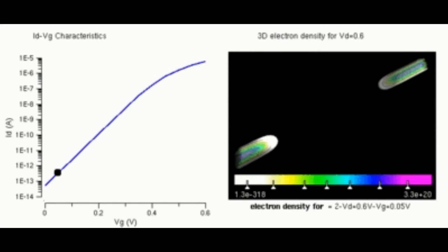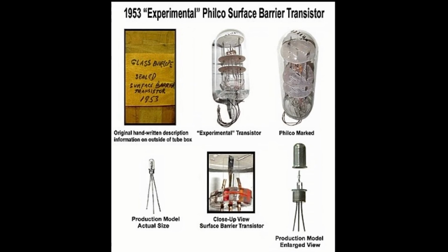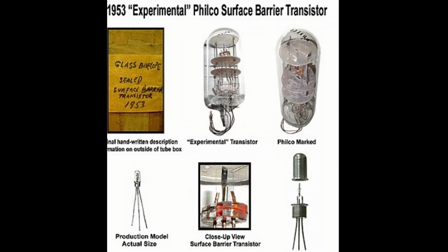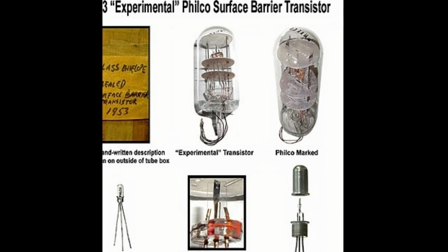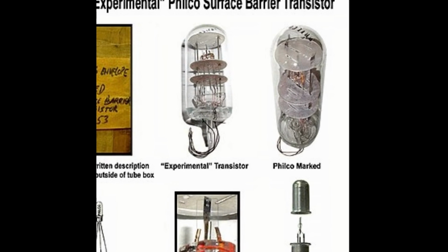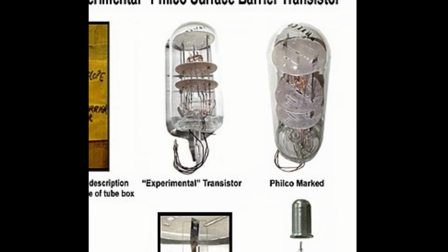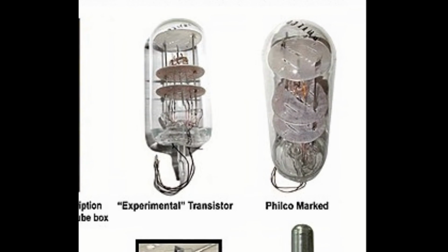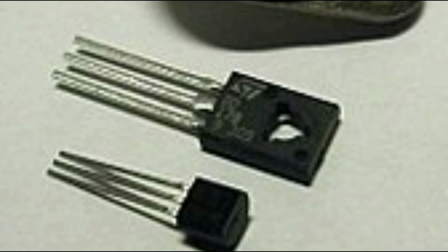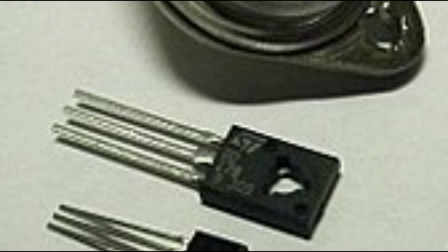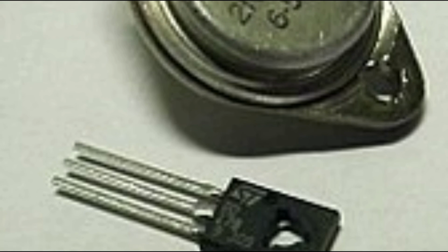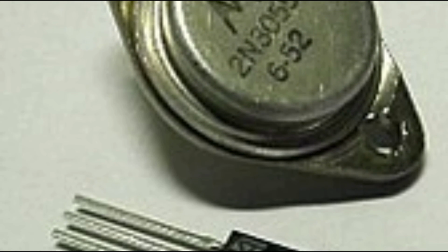Complementary devices available, providing design flexibility including complementary symmetry circuits, not possible with vacuum tubes. Very low sensitivity to mechanical shock and vibration, providing physical ruggedness and virtually eliminating shock-induced spurious signals. Not susceptible to breakage of a glass envelope, leakage, outgassing, and other physical damage.